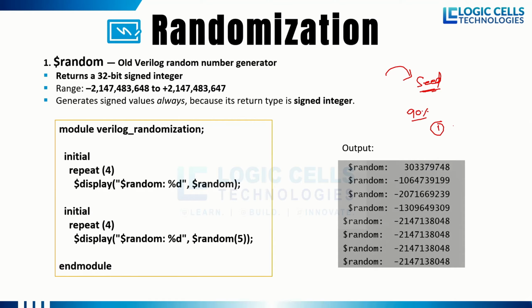If you want to debug the design, let's say again we will try with the same values. If you want to get the same values while you are also randomizing, and you want control over this randomization, you need to know what the seed is for the set of values provided. For that particular value it is failing. You need to regenerate your test case. You will be testing your design again with the same set of values, which means you need to provide that seed to the randomizer.